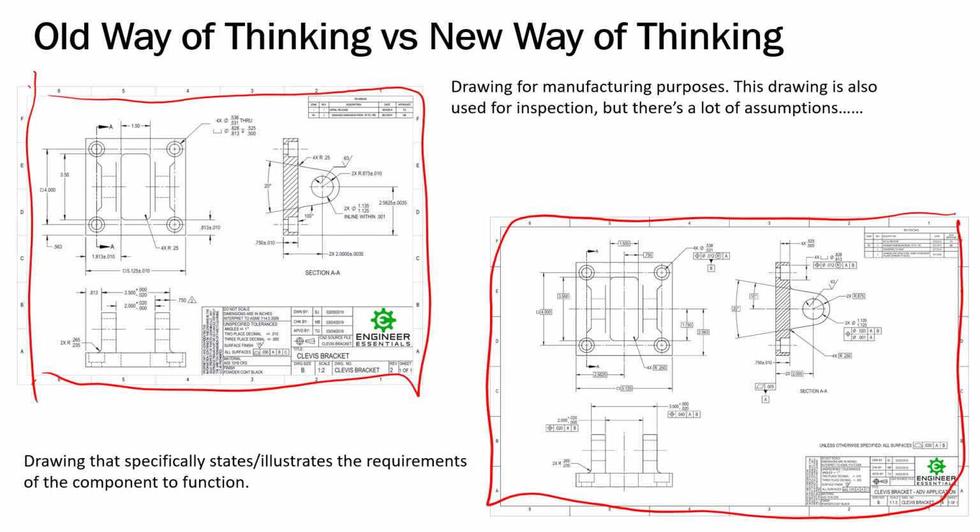On this conversion, and you were referring to the capable manufacturing processes, the question really is, did we make the tolerances any tighter? Like I said, we're not supposed to make them tighter. If we had to, then we will, but we're not supposed to do that. And when we convert it over to GD&T, we are supposed to be loosening tolerances if at all possible.